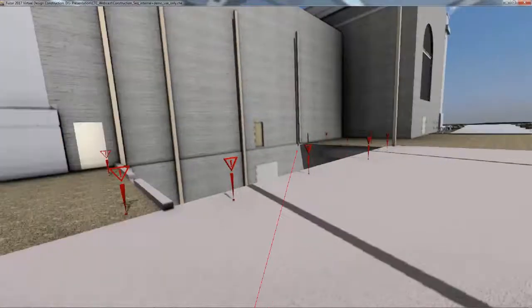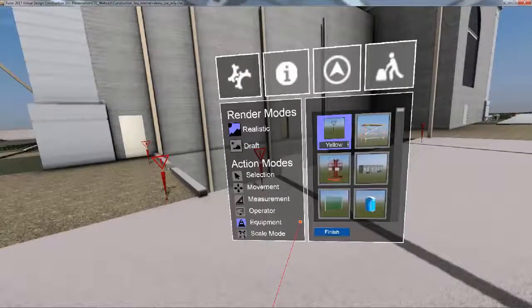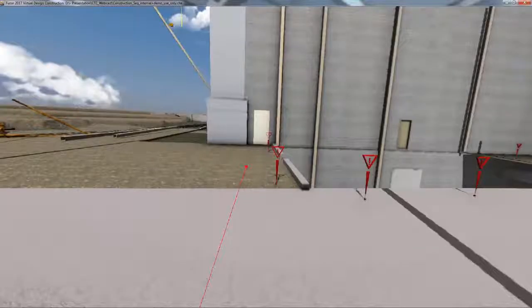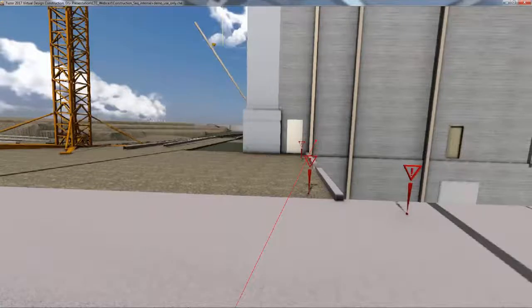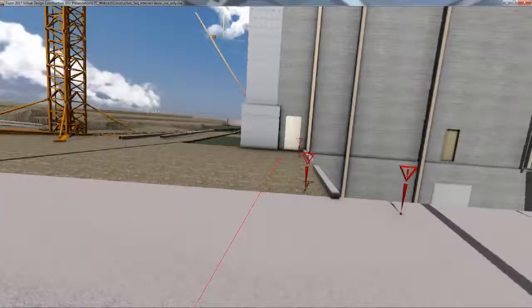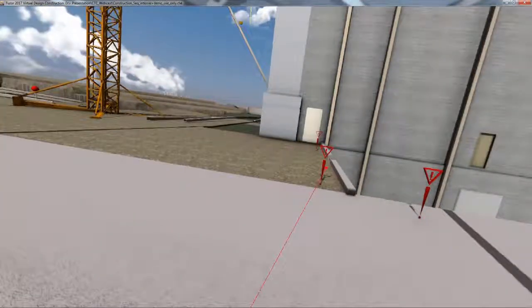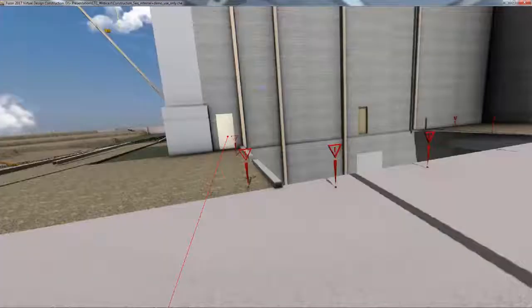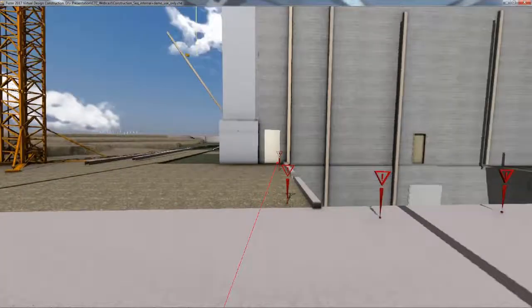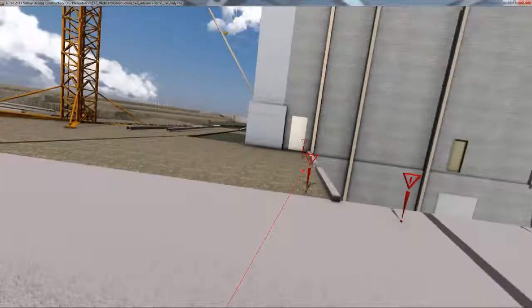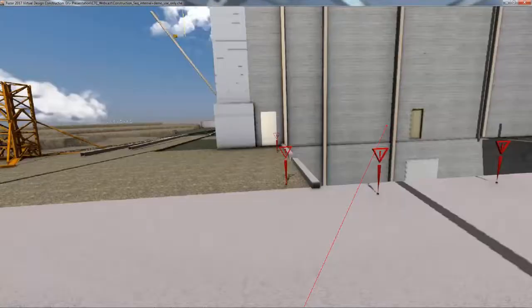Well, that's considered equipment, so I can add those into an equipment task so that when that hole gets dug, or when that's going to be going up, I can either tell my crews to put a fence line around that, or say that this is going to be a danger area. Make sure you tie off until it gets filled in, and then when the equipment task is done, I can get rid of those at the same time, and I can build that into my schedule.